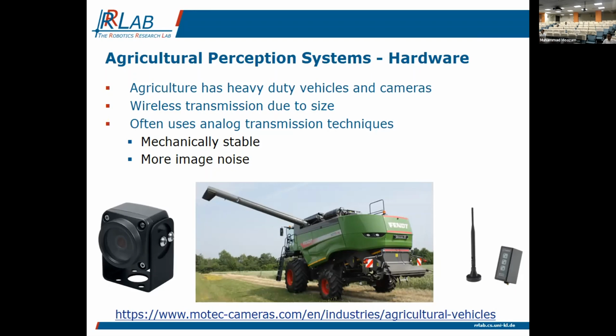Basically, we run into problems of cabling all those sensors together, because we get very long cable lengths, especially for cameras, a lot of which still function via USB. We would need repeaters. This is often not feasible and leads to many hardware issues down the line. We already faced that with smaller machines. If you saw Professor Burns' presentation, for example, our Unimog, which is an off-road truck, is maybe 1/3 of the size of this. And already with that, we face lots of problems in the hardware of sensor mounts.